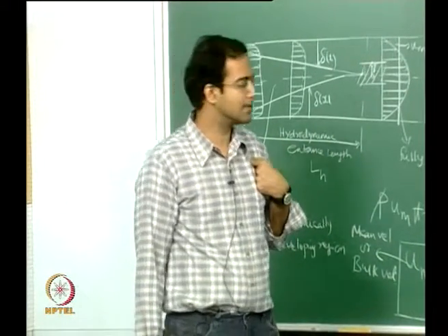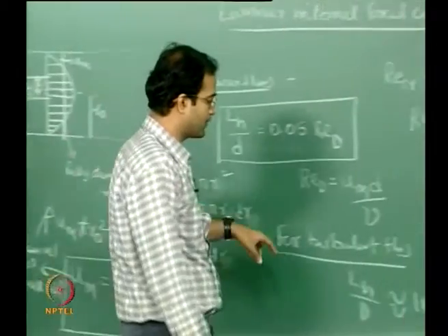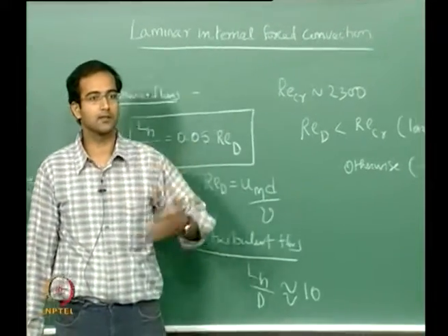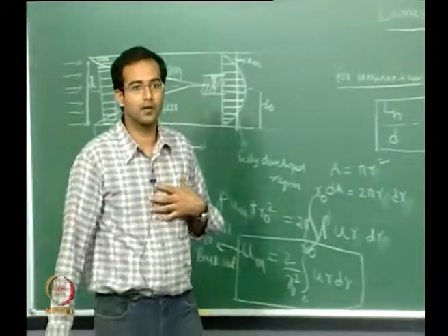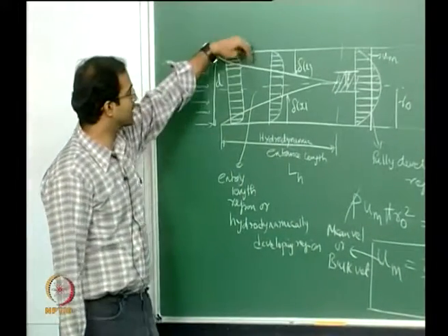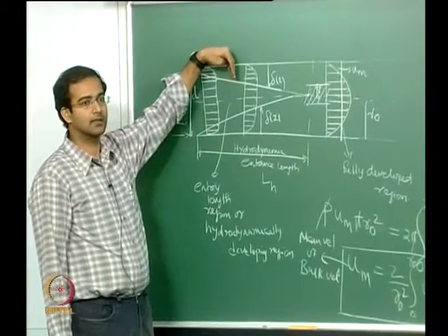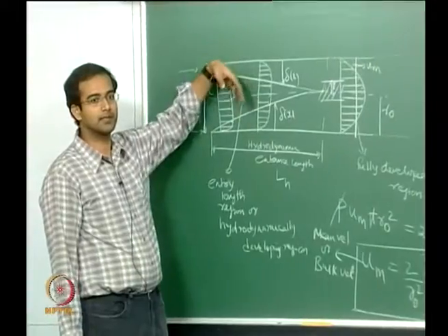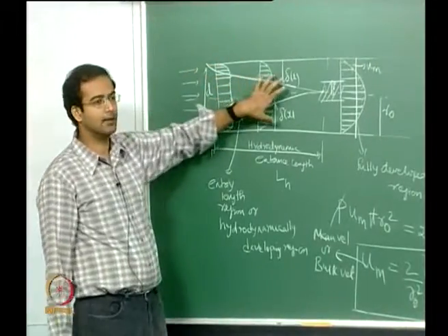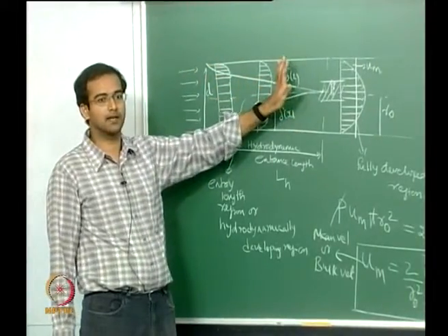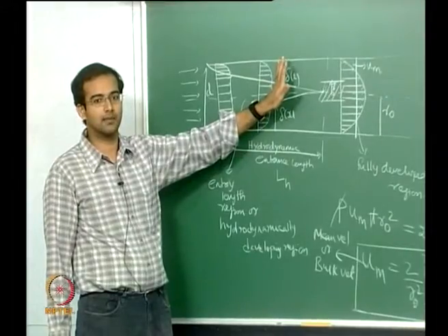The reason is that turbulence promotes a lot of intense mixing or diffusion of flow. The mixing takes place due to the gradients along the y direction. So there will be intense mixing, and therefore the profile can reach a fully developed state much earlier in the turbulent case than in the laminar case.